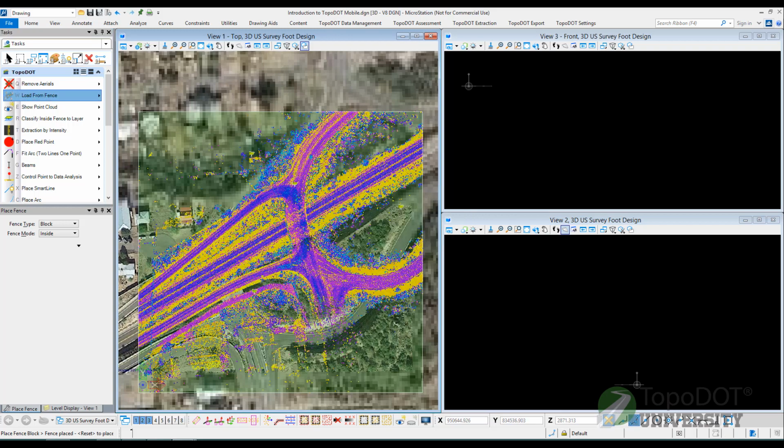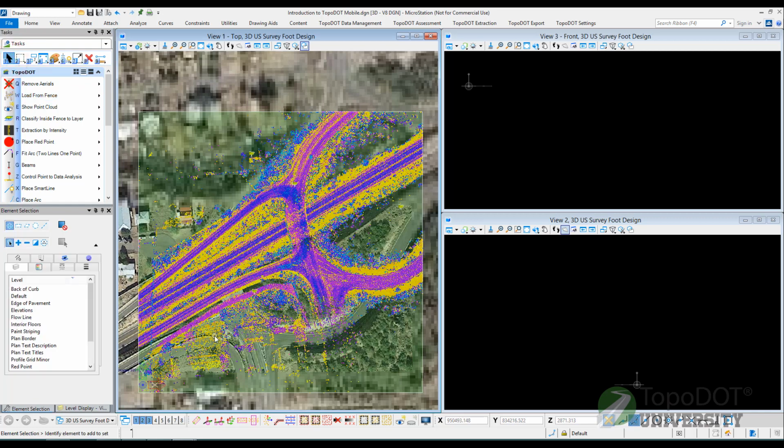As you can see, the aerial image and the data are not exactly aligned. So we're going to use the bridge to line up or shift the aerial image into the data. This is just so that we can create that center line. We're not necessarily using the aerial image to do any feature extraction unless absolutely necessary, because we don't know when the aerial image was collected in comparison to the data. It can sometimes be used to extract certain features, but mainly it's just to have a general idea of where our project is.